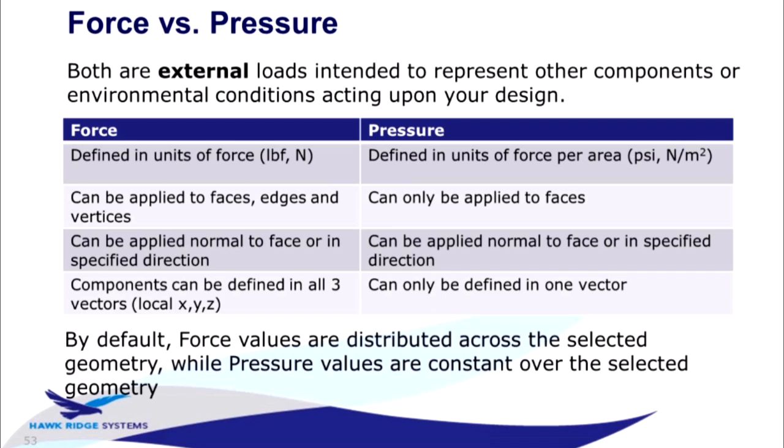And if you apply a pressure of equivalent value, you'll get exactly the same result. The main decider of which one you use is what unit you have your input information in. If you have a force, just apply a force. Pressure, vice versa, rather than doing the math to convert one to the other.